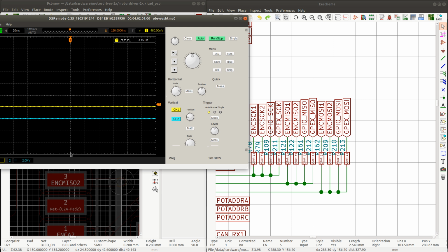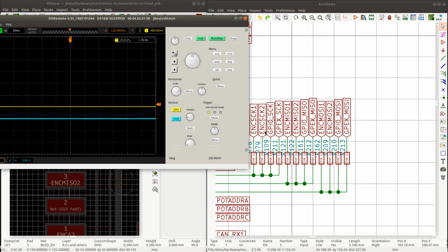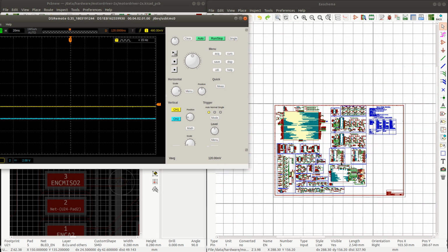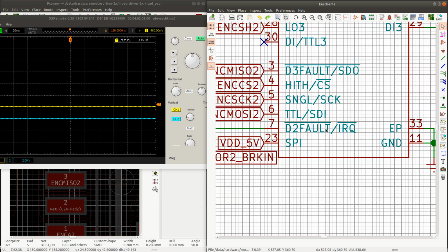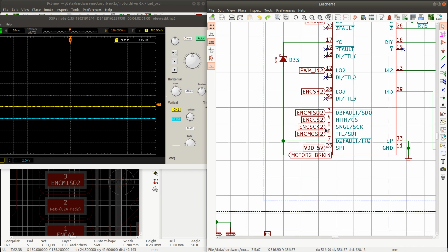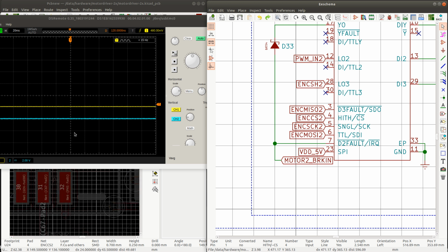It seems like there is nothing there. Because this one, I do get contact. Chip select, no contact. And then the other ones do seem to be working. Okay, so chip select on this pin here. Let's see. Chip select is on... So where is it connected on the CPU? Let's see.